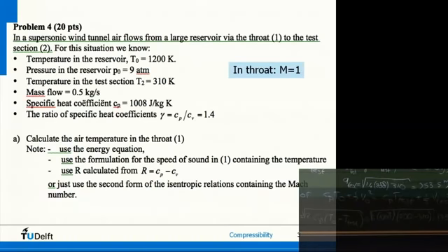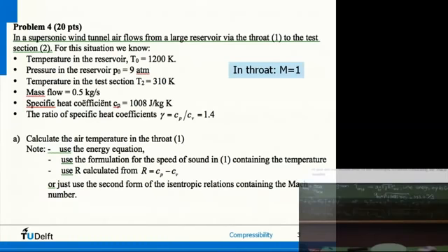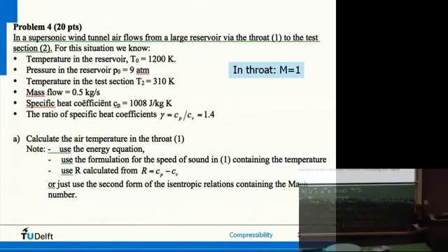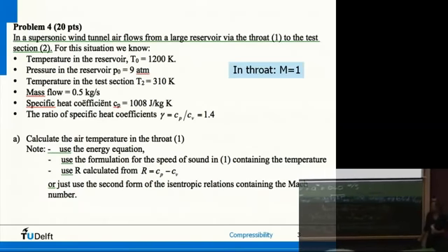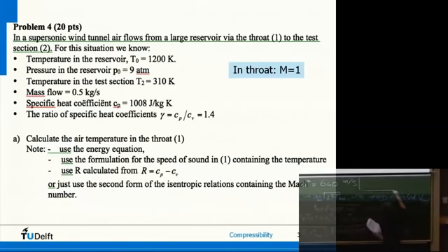So that you can accomplish, right? From 0 in the reservoir, due to the very high pressure in the reservoir, we can get to almost 1,400 meters per second. Almost there, because the question was the Mach number, right? So for the Mach number, we have to divide V over A. I'll do it up here. So Mach number test is V test divided by the speed of sound in the test section. V test we just derived, and the speed of sound we started with, 353.5. So the Mach number is 3.79.